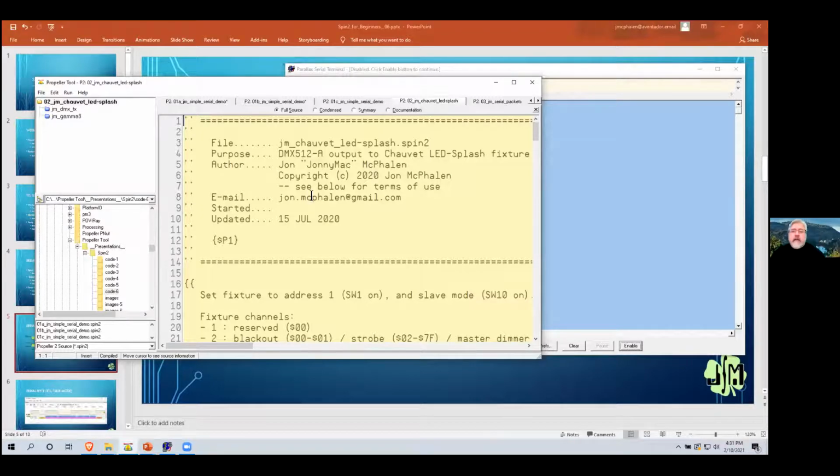Because remember, DMX is just a simple serial protocol that runs on RS-485 hardware. If I had a fancy HMI that used Modbus, I could use this same hardware. I would just use a different software module because I'd have bidirectional communication and stuff going on.